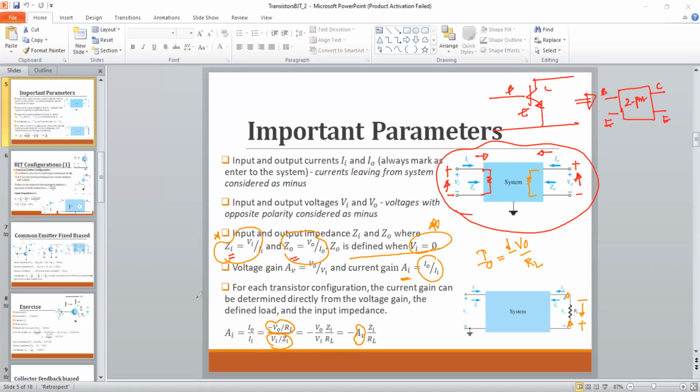So what's the real physical meaning of this minus sign? This is a gain. Does it mean that you are getting a negative gain, that you are getting a loss? No, this minus sign basically introduces a 180-degree phase shift.